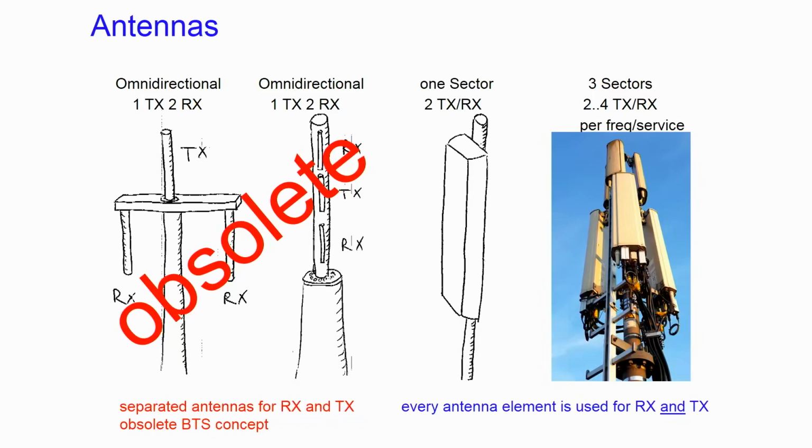In this kind of casing, there are at least 2 antennas that can be used for different frequencies. These 2 antennas have a crossed polarization, and you have diversity not with antennas at different positions, but by polarization.